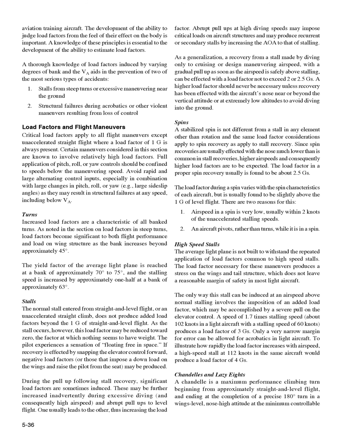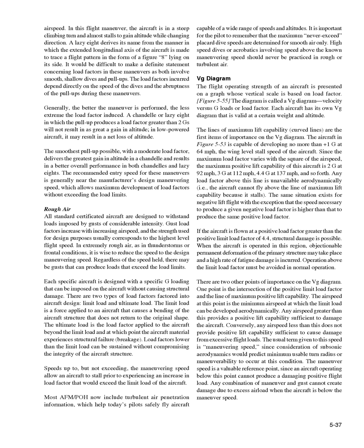Chandelles and lazy eights. A chandelle is a maximum performance climbing turn beginning from approximately straight and level flight, and ending at the completion of a precise 180 degree turn in a wings level, nose high attitude at the minimum controllable airspeed. In this flight maneuver, the aircraft is in a steep climbing turn and almost stalls to gain altitude while changing direction. A lazy eight derives its name from the manner in which the extended longitudinal axis of the aircraft is made to trace a flight pattern in the form of a figure 8 lying on its side.